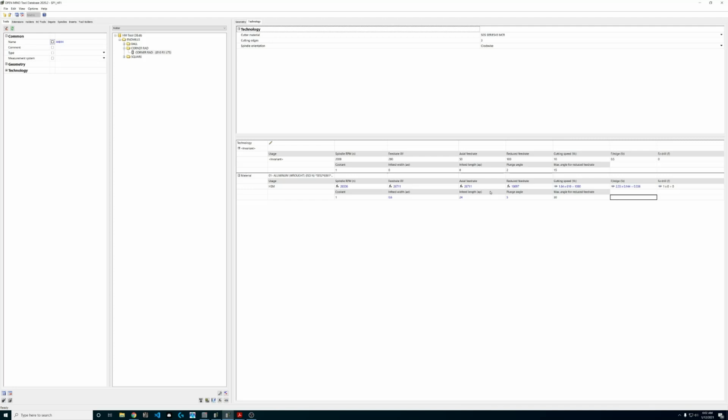Don't worry, friend. This is only the beginning, because when we take this tool and we mount it and we connect it to a holder and we create an NC tool, we can actually define at a couple different steps along the way where our maximum feed rate is or spindle RPM for that machine. And this is the beauty of it. hyperMILL will adjust these values appropriately and in sync. So we know that if instead we only have 12,000 RPM available, it's going to cap our spindle speed at 12, and then it's going to drive our feed rate off of this new spindle speed so that we're keeping our cutting data good. We've just lowered to the parameters that our machine is capable of.